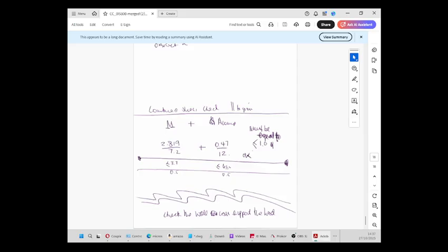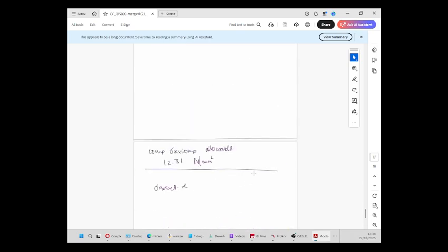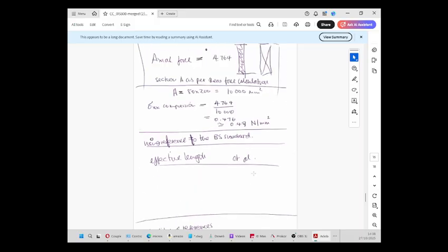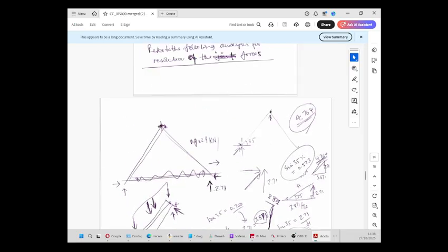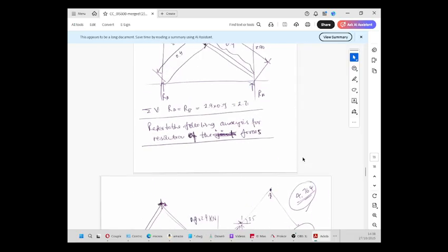But I just want to put this up because I think it's really interesting. I've never seen a coupled roof with all the forces set out properly. Hopefully this has been some use to you, even if it just makes you get interested in looking at this. Feel free to give me comments and tips and suggestions, as I want to find out what the reactions are, and then design the wall to take it. Obviously I think the wall's going to be struggling. A single leaf wall, I don't think it's going to work. It's got to be at least a cavity wall, and maybe some buttresses. Hopefully I'll go onto that in the next video.